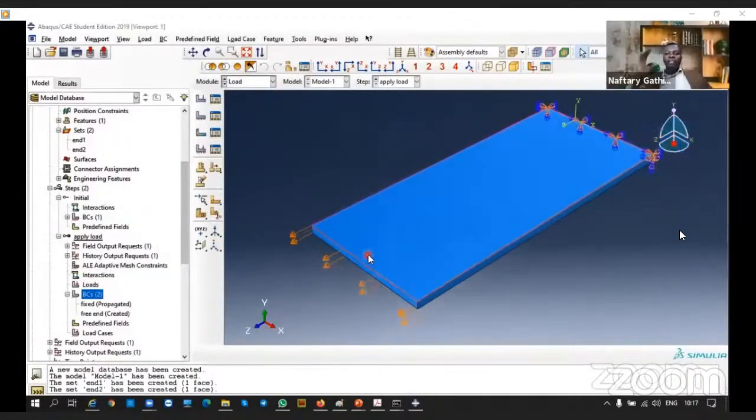Now with that, we have our structure. This is like the problem that you're usually given in a typical manual calculation. A structure, boundary condition is defined. The loading on maybe one head is given. In this case, we are defining it in terms of a pull. And with that, to do the analysis, you usually choose what type of element you want to use, and then you discretize.